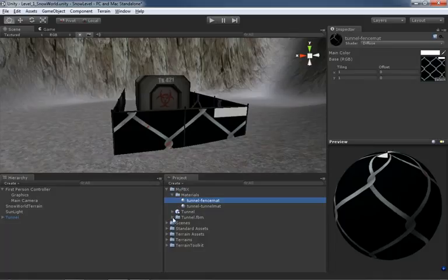Now, the textures that came along include a bump map as well as the diffuse with an alpha. So the first thing I want to do before we even worry about getting this tiling the right way is going ahead and changing the shader that we're using so that we can make use of the fact that we have an alpha channel to punch out the inside of the chain link, and we have a bump map to give this a little more life, a little more realism, make it look like something other than a flat picture of chain link fence.